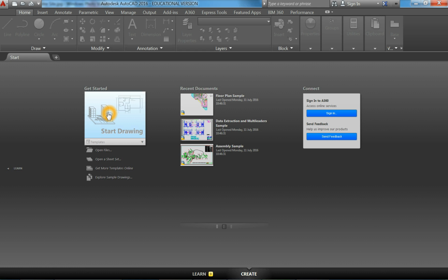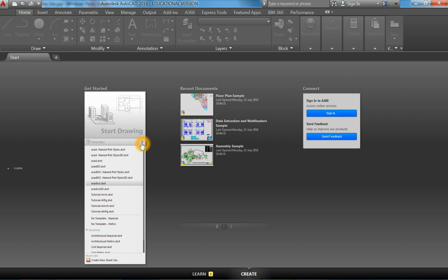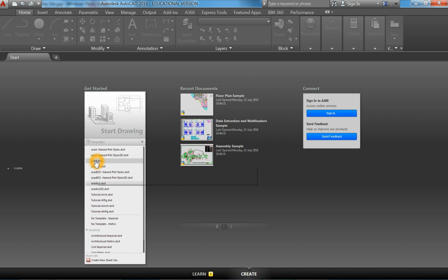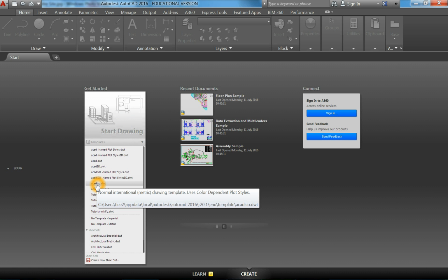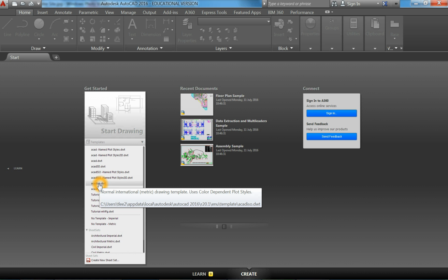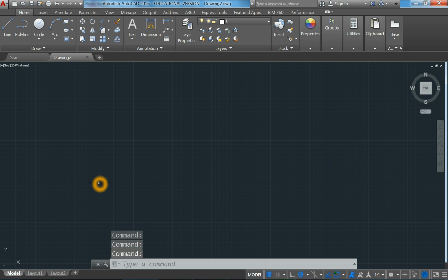And so now back into AutoCAD, I'm going to make a new file, but I'm going to click on the little down arrow there next to templates and just make sure that it's set to AutoCAD ISO, not AutoCAD, because AutoCAD ISO, you probably know, is the metric template. AutoCAD is, well, it tells you right there, feet and inches. Not everyone realizes that. That one does work for metric if you change a couple of things once you open it, but why not just use the metric one to start with, is what I think. So here you can see AutoCAD ISO. ISO is International Standards Organization, set up from the get-go to work as metric.